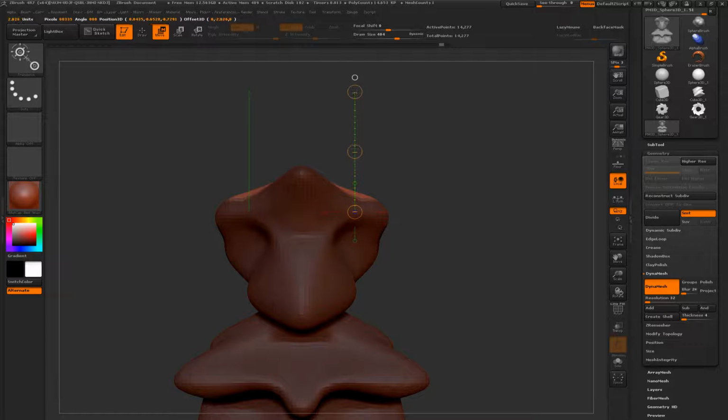So I'm going to set one over here, exactly at 90 degrees. You can also have it at 100 degrees, 90 degrees. Click, hold down Shift, and now you can pull it in a straight line. All right, so this is the transpose line. What it does is basically put up three dots over here, and as it is right now, we have it on move.